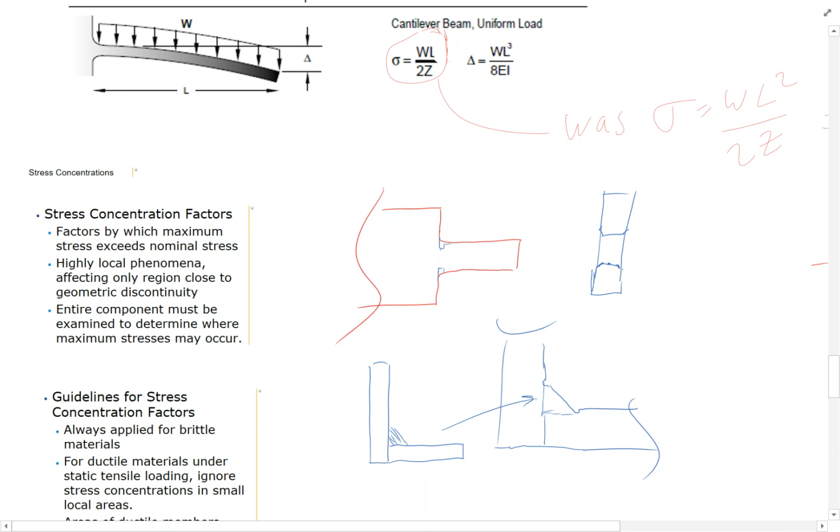It really becomes apparent when you do a finite element analysis, and unfortunately I don't have SolidWorks on this computer. I need to bring my other computer to do that. But you'll see areas of high stress using color, like all analysis packages typically do, and that's where you're likely to get fatigue failures initiated. That's where fatigue failures initiate.